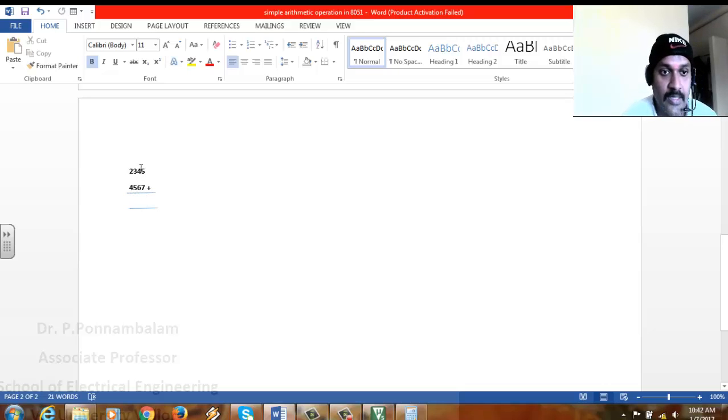So practically we'll have to add it in such a way that initially we'll add 45 and 67, then 23 and 45. In case you are getting a carry, that carry should be carried over to this 23 and 45. So we'll try to have a greater number over here so that we'll get a carry. So 23 we'll put as F5, and maybe this 67 I'll change to A7. Okay, so these two are hexadecimal numbers.